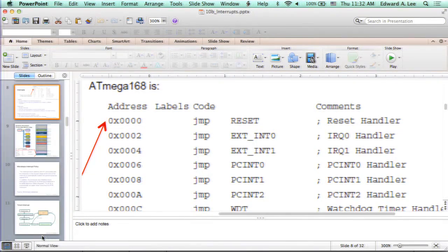So is it clear how the mechanics of how this works at a low level? Yes? So what if both of the interrupts trigger at the same time? Well, that's very dependent on the processor. You'd have to look in the manual to see what happens. Intrinsically, if you're talking about 2 voltage level transitions occurring at the same time, one could be arbitrarily earlier than the other. So there's no necessarily synchronous notion there. So you could have a race condition, and it could be just arbitrary which one will be handled. But very good question.